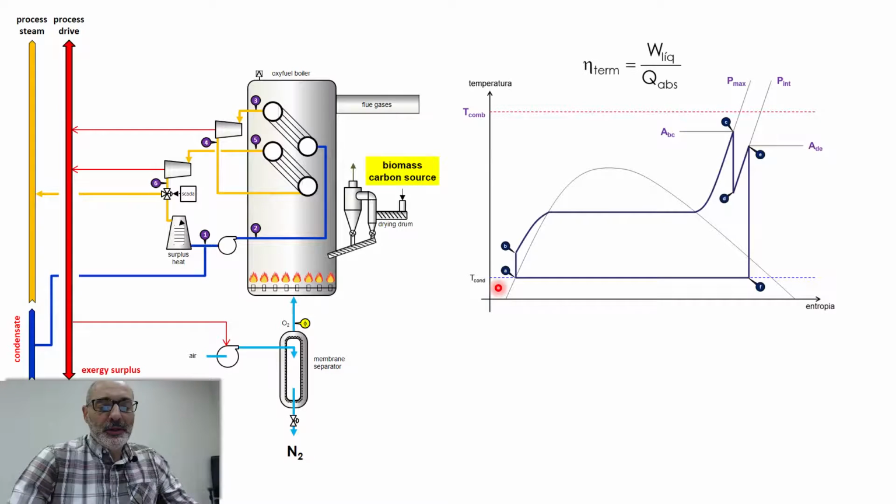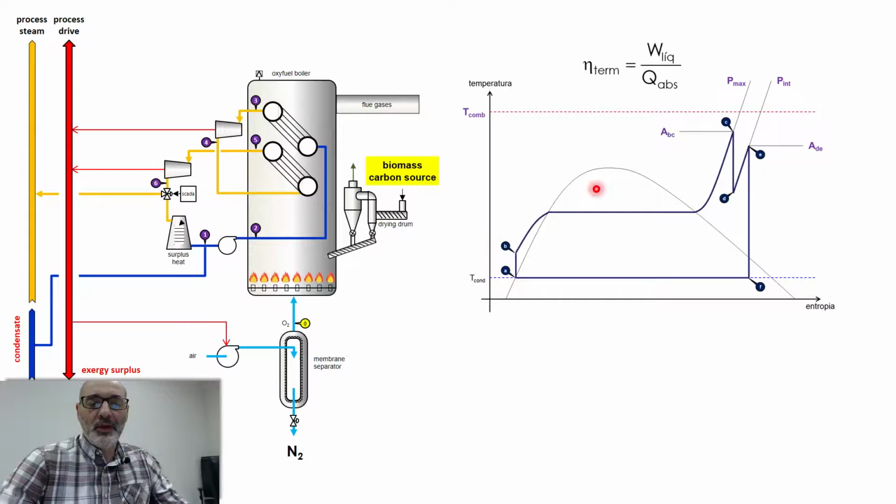Well, the thermodynamic cycle is a Rankine cycle. We're not going to do any calculations today, but just to show you, it's a Rankine with reheating, as it is shown here. So virtually, if it's an oxy-fuel combustion, at this point here you have CO2 and H2O. You don't have nitrogen because you're using O2.